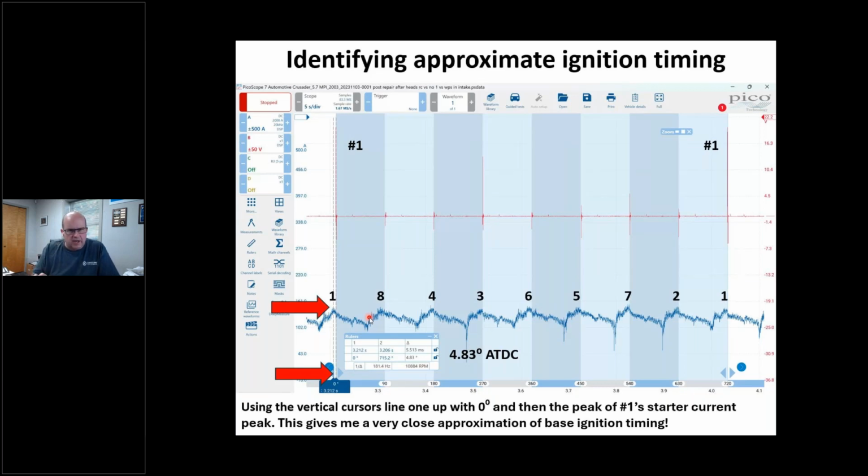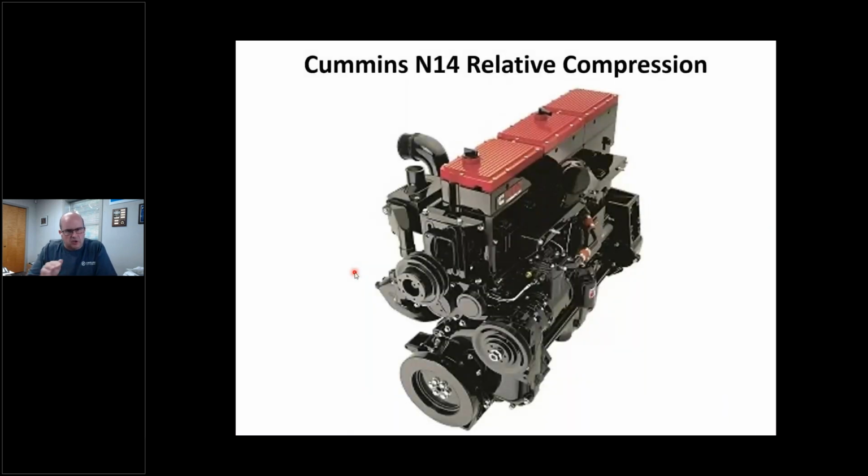So I always tell guys to do this. Okay, you should always do this test. It's very easy to do, and like I say, it's not degree wheel accurate. But if my spark line's firing somewhere over here in left field, I know that engine's got no chance of running, because if that spark or diesel injection, whatever, is happening 60 degrees retarded of TDC, it ain't gonna fire. With that said, it's all diesel from here on out.